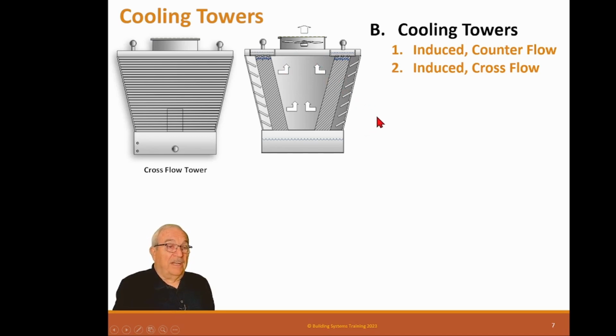I used to calculate every tower I modified with a VFD and had all these calculations. But after a while, I said, why am I doing this? Because every one of them showed they pay back in 3 to 4 months. So there was no need to do that calculation to prove to an owner it's going to save energy. Every one I've ever done pays back in 3 or 4 months, so you need to put a VFD on that.